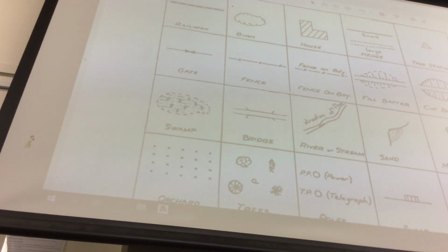The bottom of the manhole, make the walls about 100 thick, and make the concrete at the bottom about 100 thick. There is normally a gap here that pokes in by 100. There's normally a gap here of 100 as well. That's where all the sludge gathers at the bottom of the manhole.